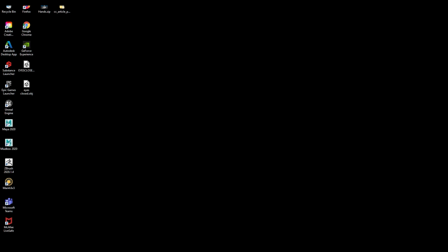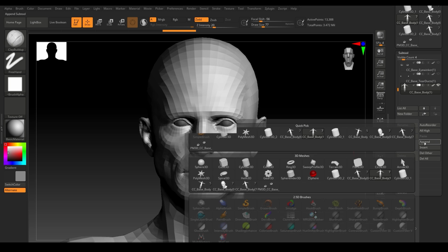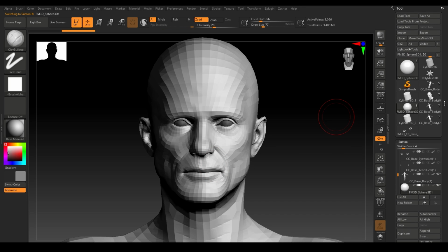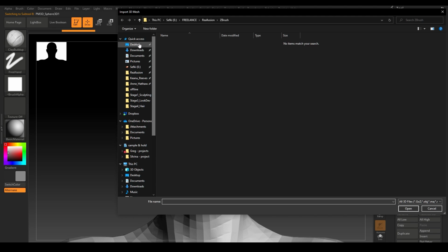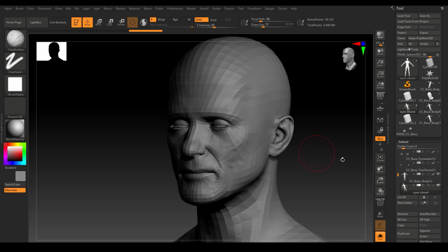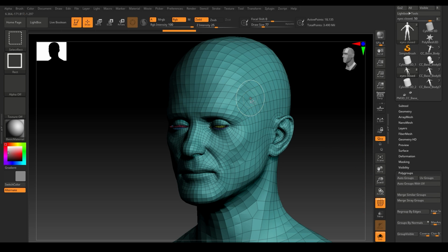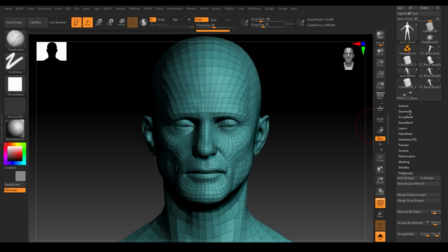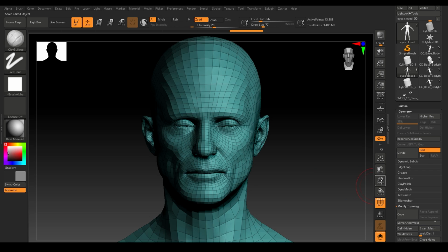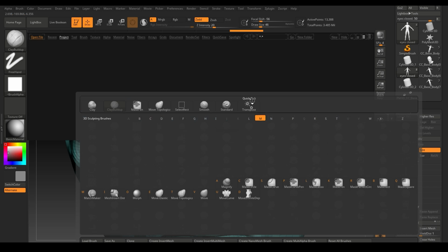Okay, so now back into my ZBrush scene here. First I'm going to append this new eyes closed model. Okay, and you'll notice that there's the eyelashes and it also has the eyes and the teeth, which we don't want. So real quick, I'm going to polygroup, auto group, select this, and then modify topology, delete hidden. We can also make some changes to the eyes if they look kind of messy like this. So go into